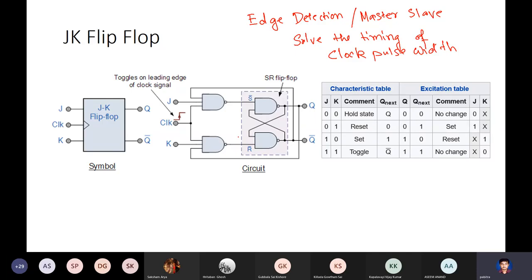Okay. So what I will do is the following. Let's take the flip-flop. So by the way, this is the symbol of the flip-flop. This is called a clock. So what I will do is that, in fact, this is not the clock. This additional wedge is there. I'll tell you what this means. This means that if you look at the timing diagram, this latch is enabled or activated only on the up edge. Only on the up edge of the clock.